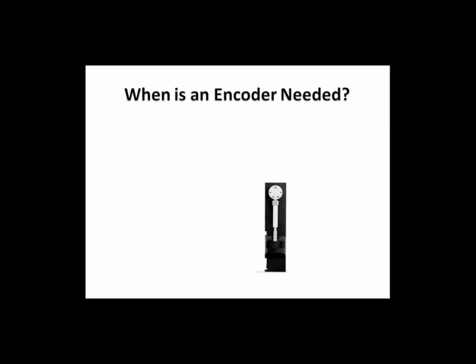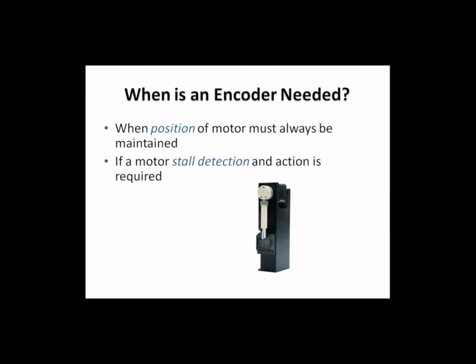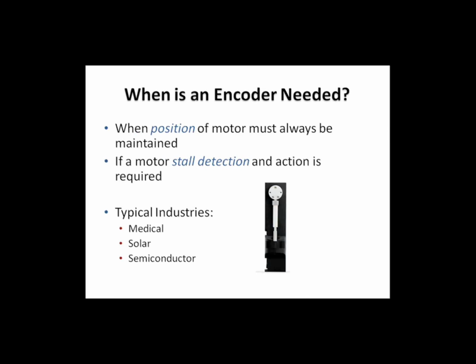Hi guys, this is Ryan again. Okay, so an encoder would be used in situations where, let's say you're designed for a particular torque range, and your application, the end user, may exceed that torque design point. So if that's the case, then you definitely want to have an encoder to know when you've gone above and beyond that design point, so that if there's a stall, you could know about it and then make a correction for it. For example, in the medical pump shown here at the bottom, if the valve is at the top, the circular device is just a valve, if it is pushing different types of fluids and crystallizing, then you definitely need an encoder to break away that torque, or if you know that the system is stalled because of crystallization, which is outside of the normal design point of that unit.